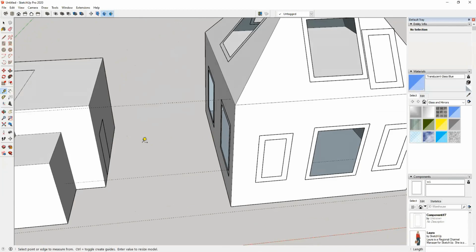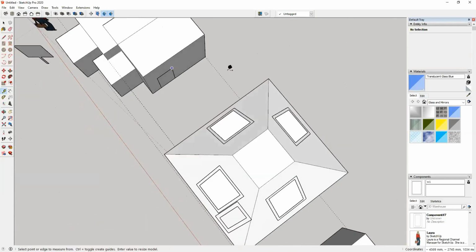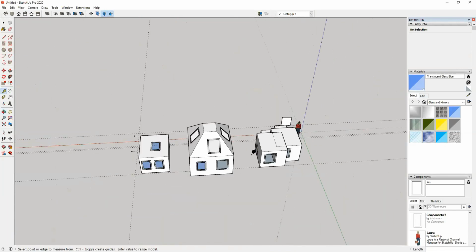So that means if I click control once, you don't see the plus or the guideline, that means we are only measuring the dimension. Okay. Now it will create a guide. So guides will be very handy for us when we start creating our objects.